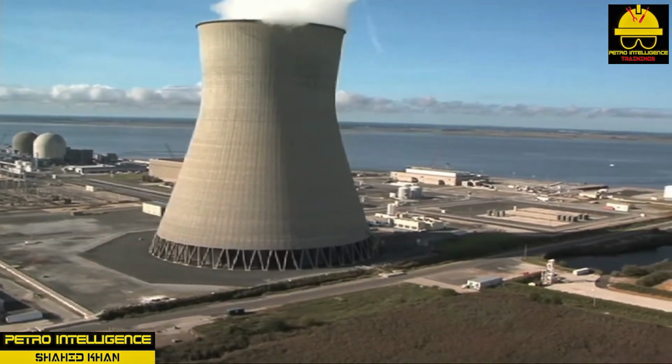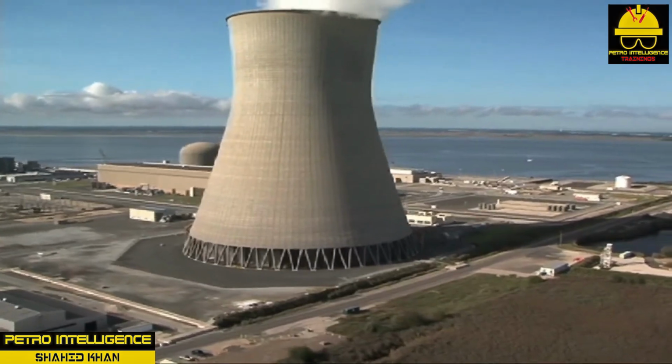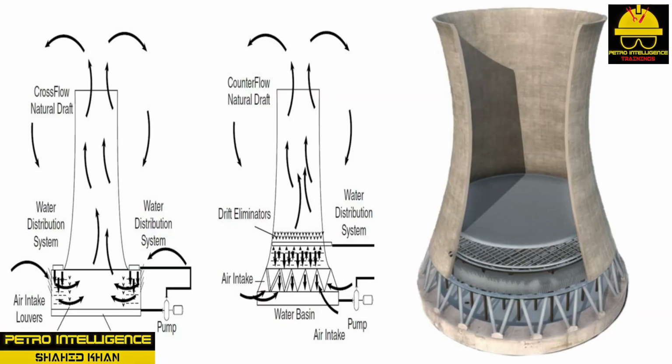During operation, a natural draft tower resembles a large smokestack. Air enters the cooling tower at the base and is directed into the internal fill pattern. As hot water drops through the fill, it is exposed to the cooler air. Density changes inside the chimney create the required upward draft. Heat is removed through the chimney. Natural draft efficiency is linked to the relative humidity and the temperature of the outside air.